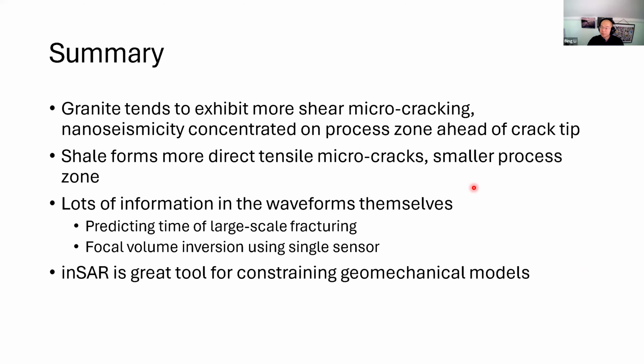So you first load by uniform compression. And when the pads go to yielding, constant stress, then the gaps close, the bending moment acts, and the crack is growing. And what is beautiful is that the initial state and the final state are also statically determinate, because when the force is constant from the yielding pads, it's the same thing as a gravity load. So it's easily interpreted. A number of people do it, but not in this field yet.